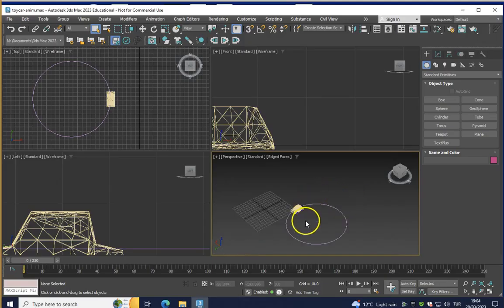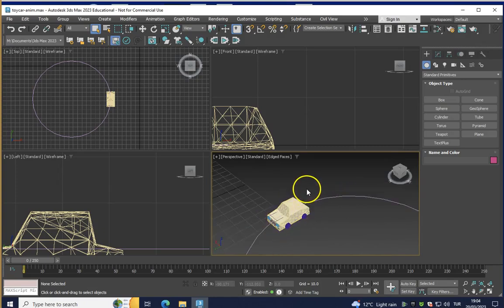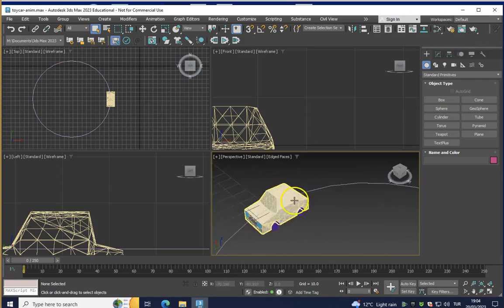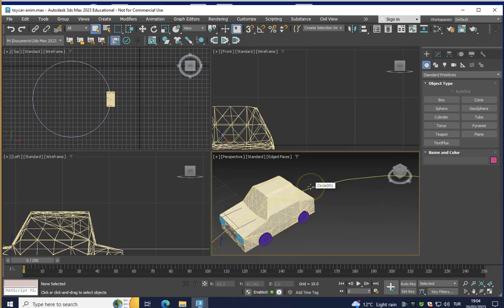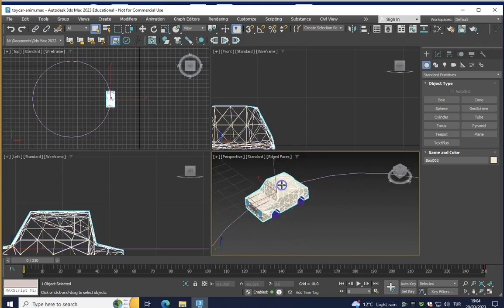One of the main issues with the models in 3ds Max and the importing options in Unreal Engine is that you need to have either four-sided polygons or triangles in your model.